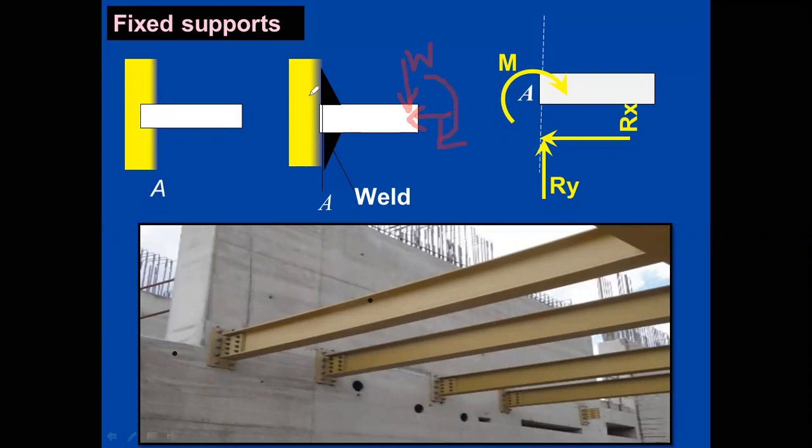For example, we know that the fixed support is the one where the support has been fixed. So here you see, against this vertical force, there is a development of a vertical reaction upward, and due to the horizontal force, there will be a resistance force developed horizontally, and along with the moment, there is a development of an anti-clockwise moment.